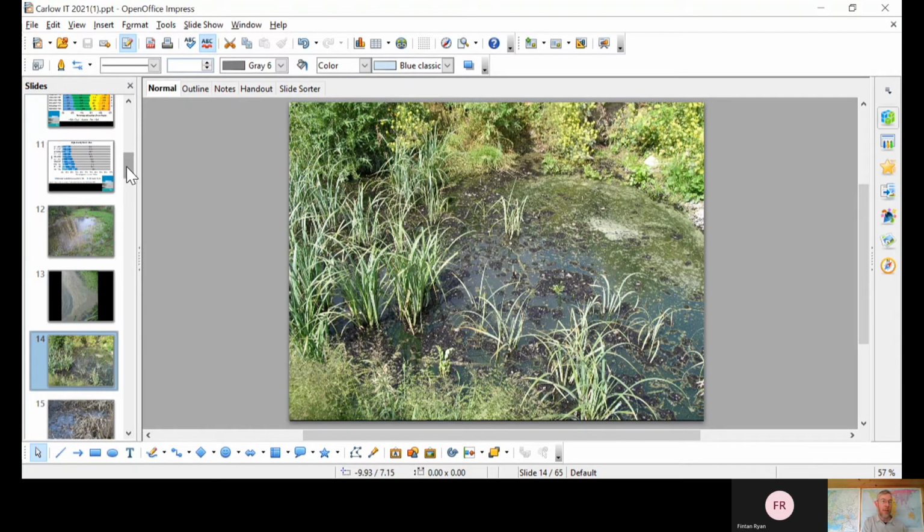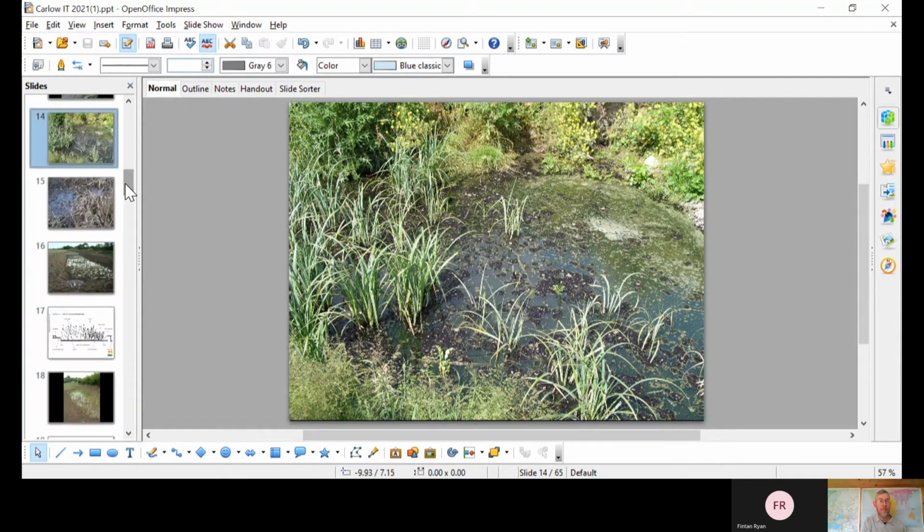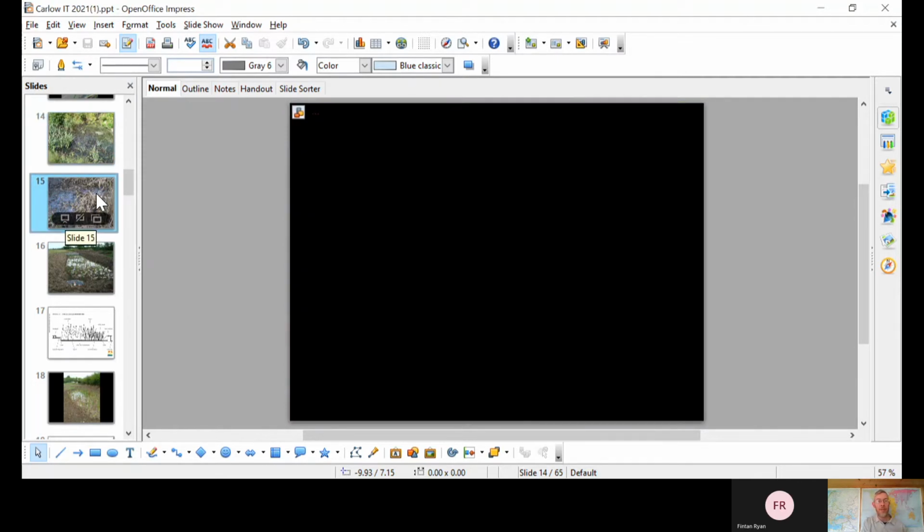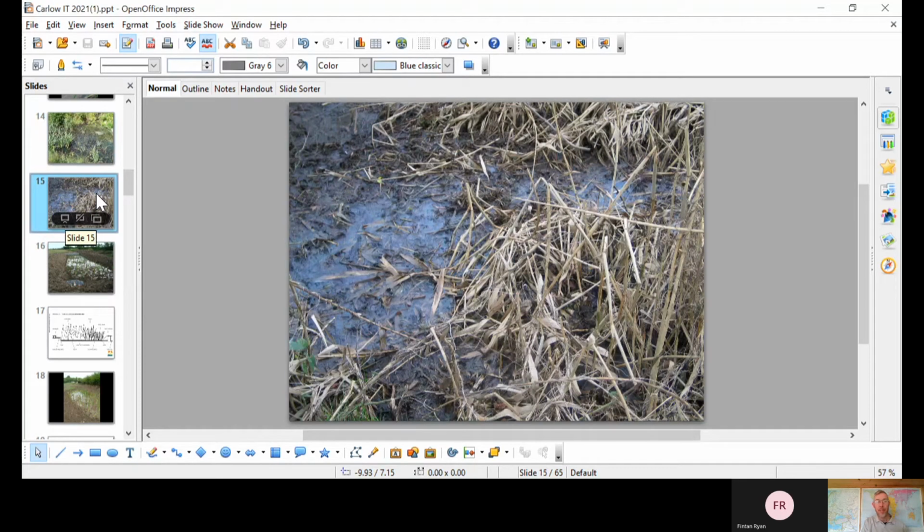And you can see very quickly how you begin to get a lot of the mechanisms that are also active in conventional sewage treatment. Your filtration, your settlement, and nutrient uptake of various forms. And even in the winter months, the constructed wetland can still function. The wetland plants growing on the surface fall into the water body, and basically it acts as a large horizontal flow fixed film filter. So you've got your fixed film media, which is your leaf litter and your plant debris, and then the bacteria build up around those as your microbial scum layer. And as the water moves along through the wetland, it's those microbes actually that do a lot of the work.